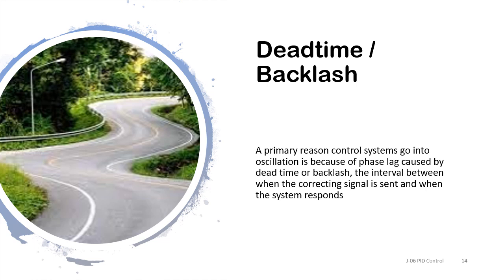A primary reason control systems go into oscillation is because of phase lag caused by the dead time or backlash, the interval between when the correct signal is sent and when the system responds. Consider the case of driving at a moderate speed down a narrow winding road. You would be making continuous, small back and forth adjustments to the steering wheel in order to stay in the